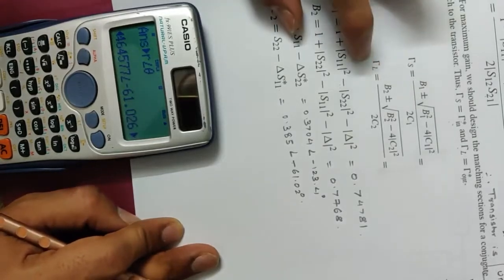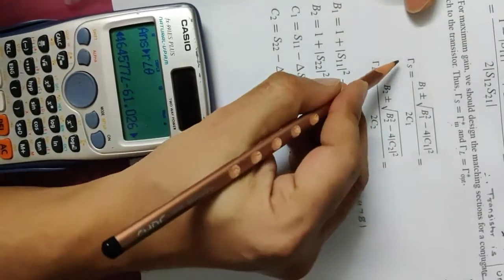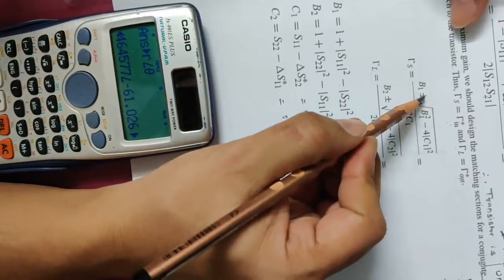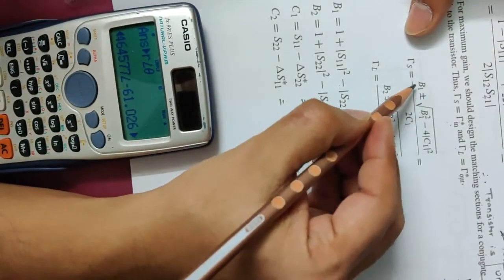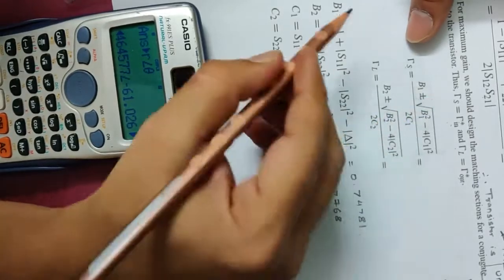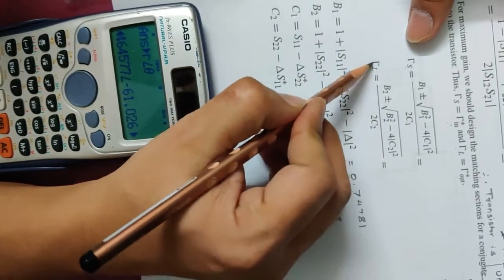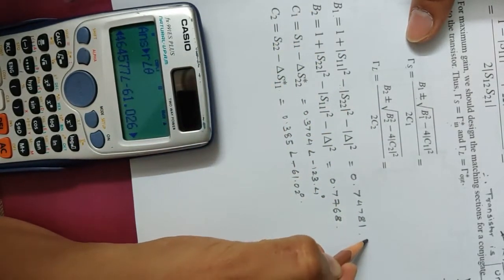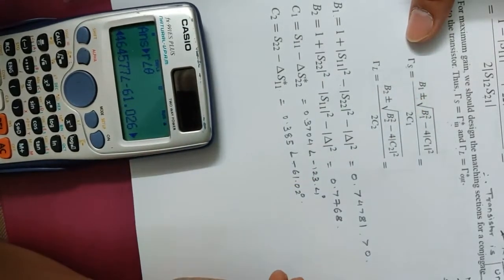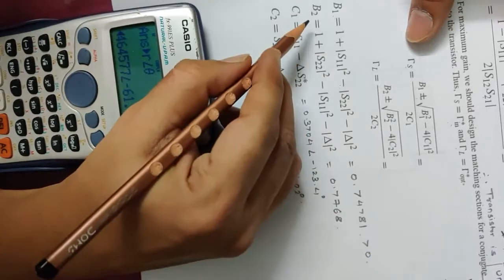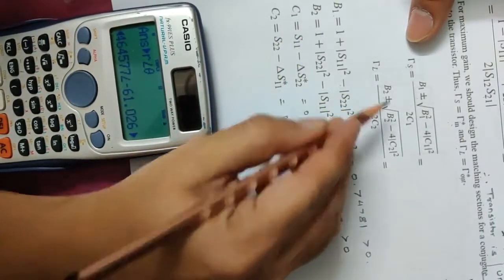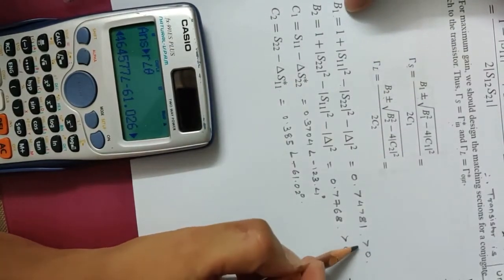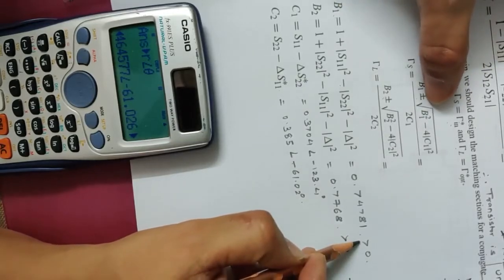Now one has to calculate gamma S and gamma L. Now be careful, in gamma S we have again these two possible options, either positive sign you have to consider or negative. So remember, the sign selection for gamma S depends upon the value of B1, and the sign selection for gamma L depends upon the value of B2. Now B1 is greater than 0, so the sign that has to be considered is negative. Again, B2 is greater than 0, so the sign for gamma L that has to be considered is nothing but negative. In case B1 turns out to be negative, then one will consider the positive sign over here.